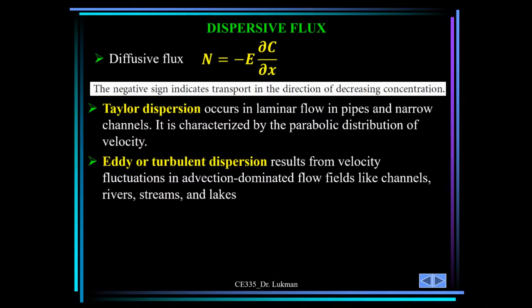We know the velocity within a pipe varies parabolically, parabolic shape, minimum or zero at the boundary and maximum at the midpoint, due to viscosity or shear stress occurring at the boundary. Viscosity is what causes the shear stress, and the shear stress is maximum at the boundary, minimum at the midpoint for pipe flow.